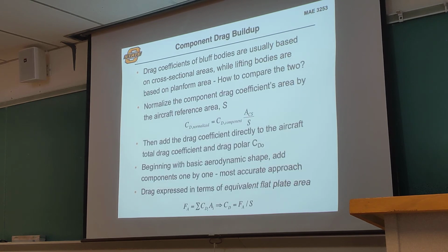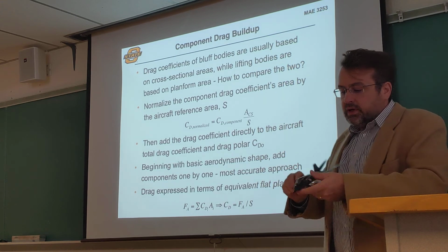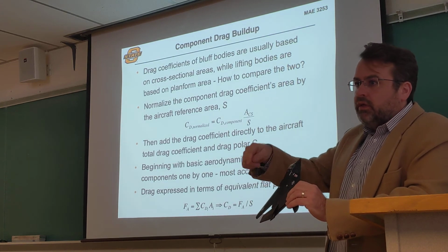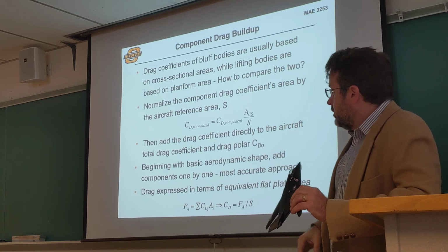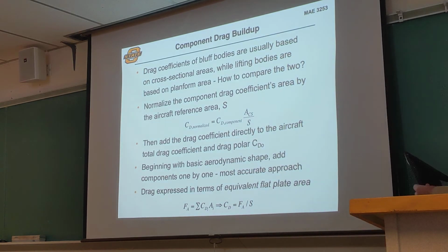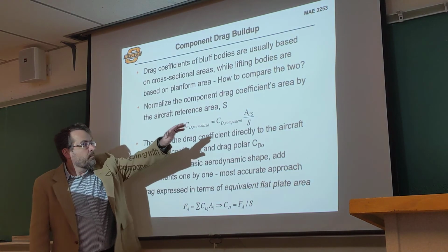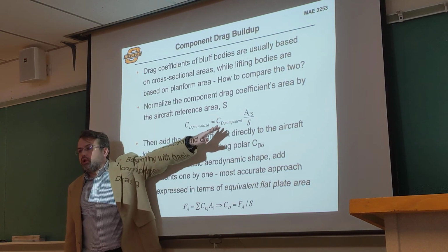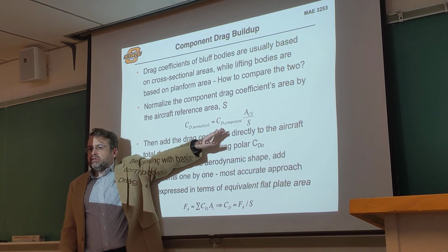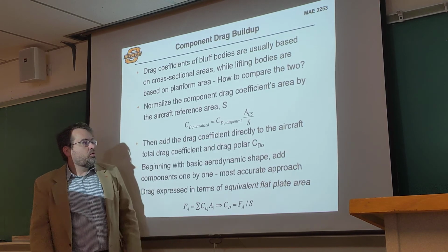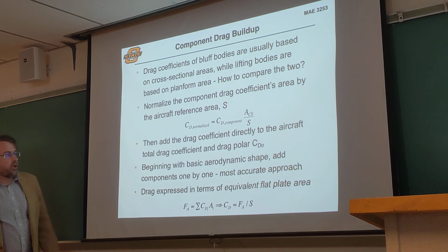Really this boils down to taking something like this, figuring out what the individual drag components are going to be, and then adding them all up, just like we've already talked about for the homework for the Piper Cherokee. So this is the homework problem where we look at what my drag is for an individual component, such as an antenna or my wheel pants or my landing strut.